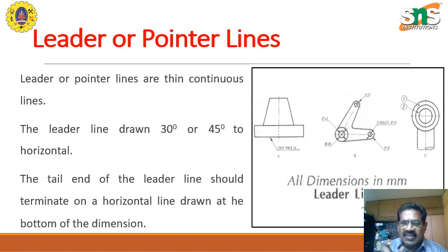Such kinds of notes can be written on this. So for that you use a leader line. A leader line has a text there, and it also has just one open-ended arrow. The other side is open; one side shows the arrow. Or you can have these balloons there. Here this part is part number one, and this part is part number two, and that is what it clearly tells us.